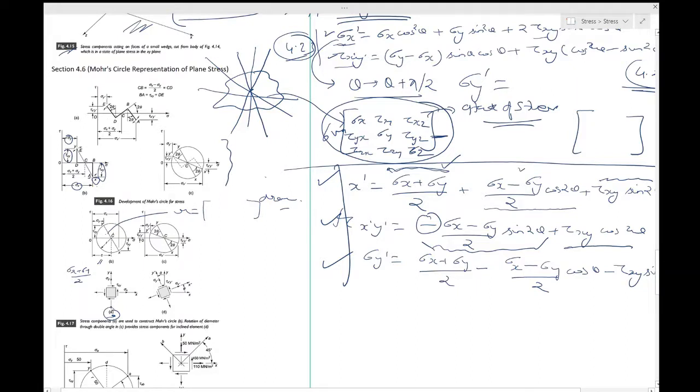These stress components apply to the same physical point O in the body but are with respect to the axes x dash y dash, which make an angle theta with the original axes. You want to find the stress components in this new coordinate system.